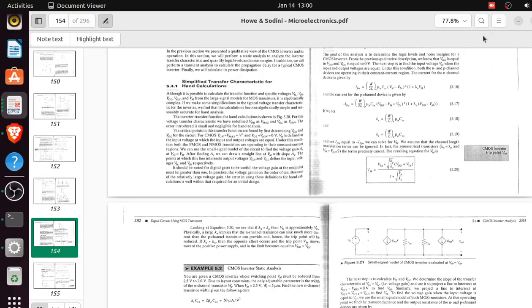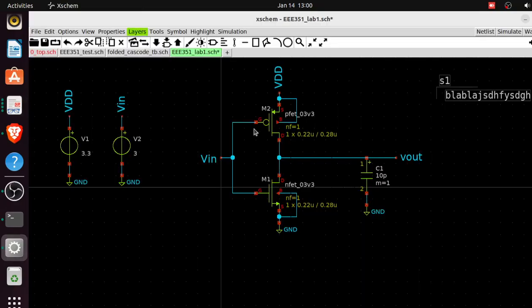What's the physical implication? You have the PMOS and the NMOS. By mobility, electrons having more mobility than holes, it means NMOS will be quite faster than PMOS. So you're putting two things with different speeds to work together. PMOS is not as fast as NMOS, right? But you want them to operate together, so you need to compensate for the inherent slowness of the PMOS.